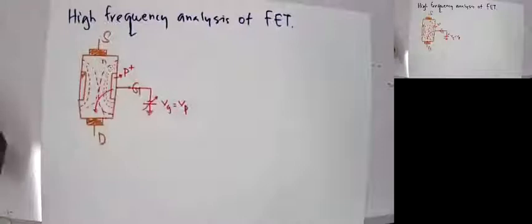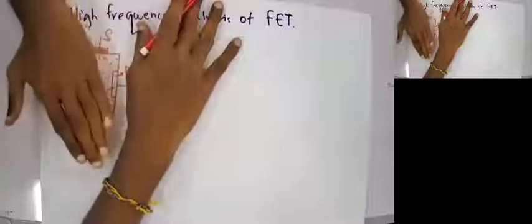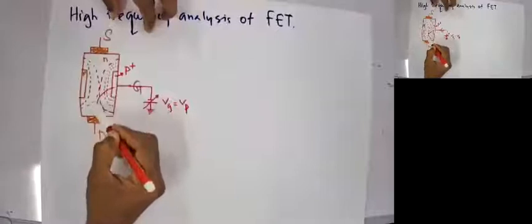In a BJT, we have the base current, IB, which is going into the transistor and joining with the collector emitter current, and then your emitter current will be IB plus IC. But in a field effect transistor, your input side is almost completely isolated from the output side. There is only a leakage current, only a reverse saturation current of this PN junction, a very small leakage current.